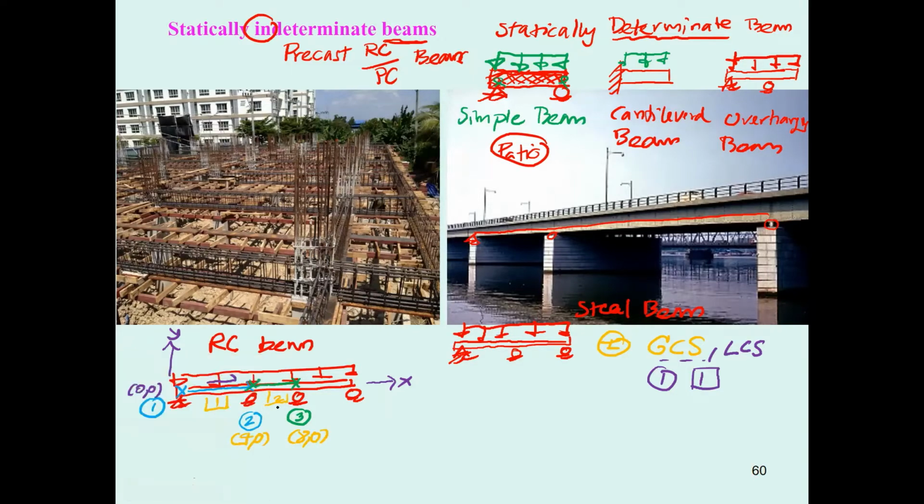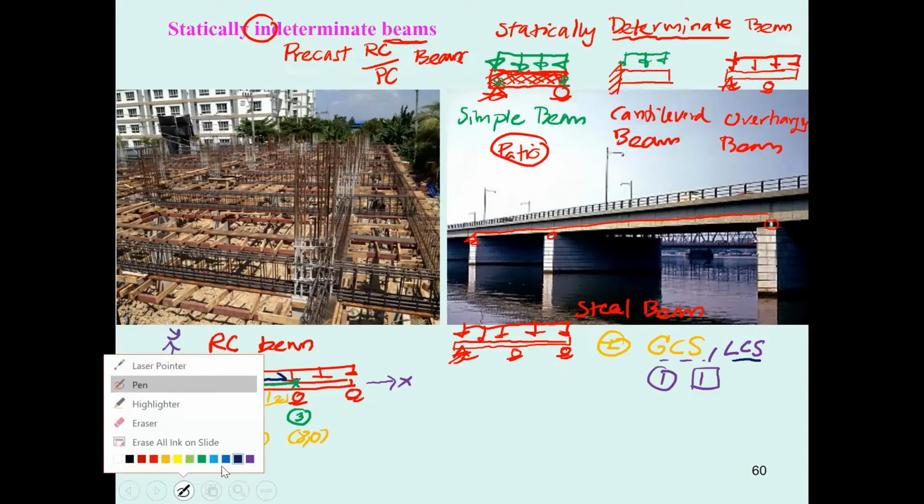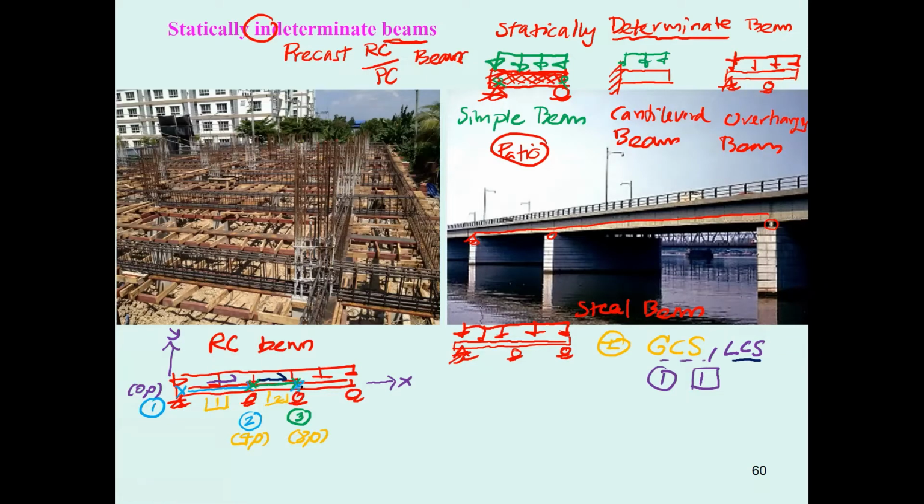The direction that you use is in this local coordinate. Again, if you move it a little bit further, you mark this one, and that is node number 3, until you reach over here. You get this one, node number 4, and the computer will know this is member number 3, and this one is going to be the local coordinate.